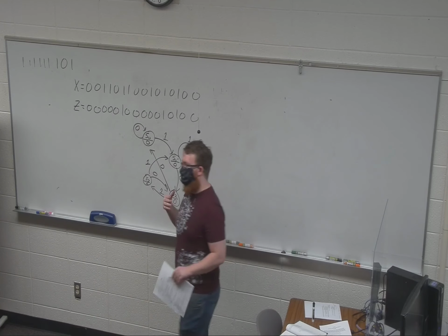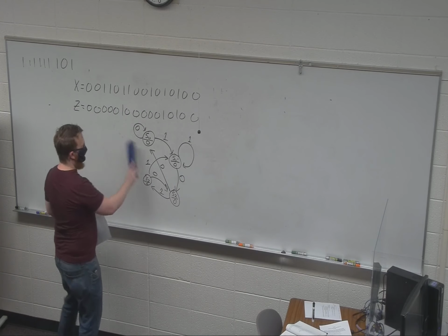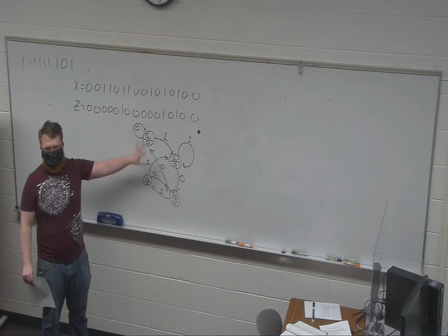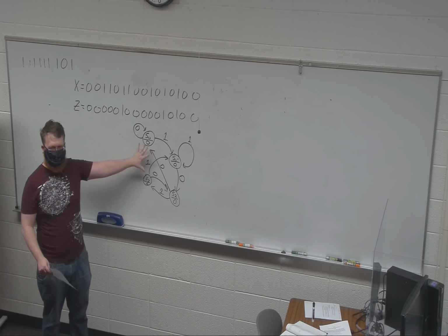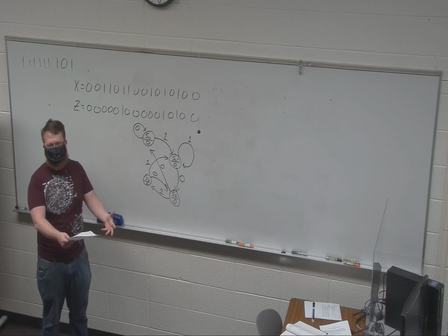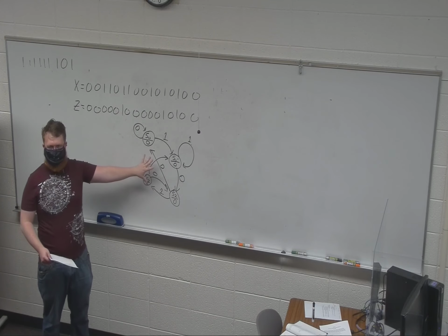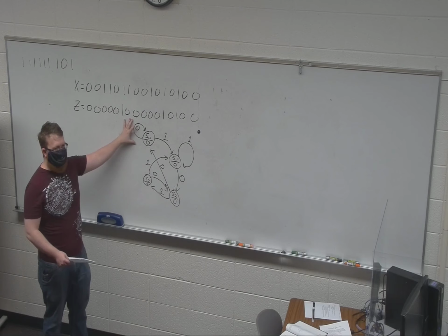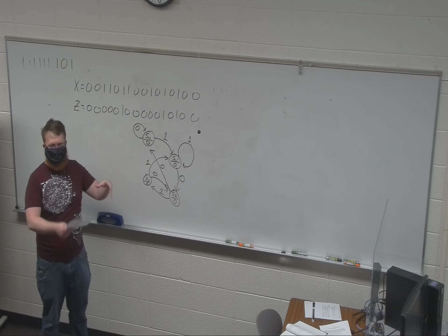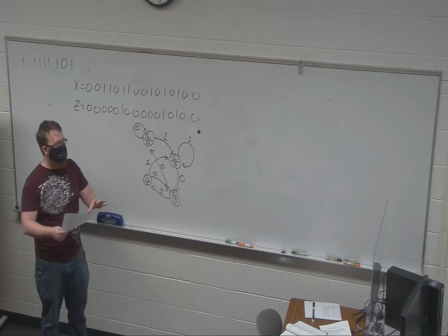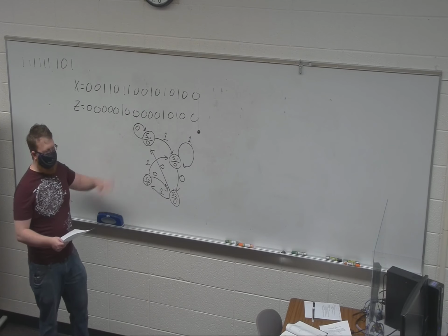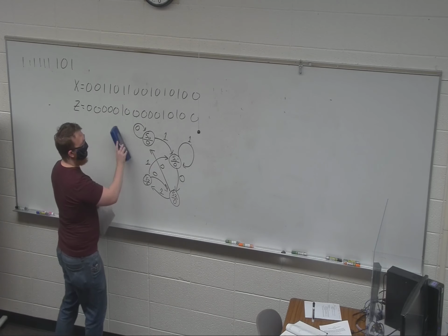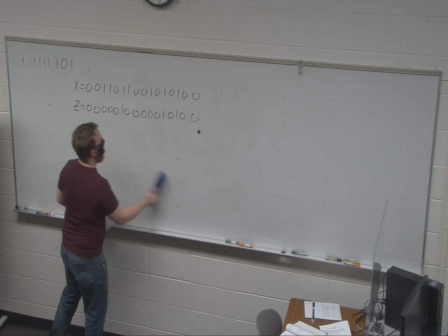Okay, so now we have these sequential circuits. We have these states. If we know each state needs to do something, we can go in and design these, and when we hand it off, if we have a good state diagram, whatever engineer we hand it off to has a good picture of what the machine is trying to do, and only has to worry about the individual blocks. And so there will be people in some large projects who just draw the state machine and hand it off and say, I need these states and I need them to work in VHDL. We'll usually refer to that as a systems engineer, but these are very helpful in design. I really can't emphasize enough how useful the state machine is.